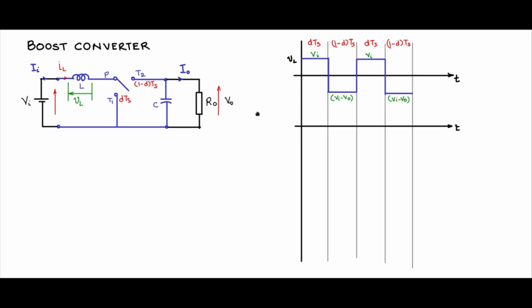So now let us see the current waveform through the inductance. I am drawing this average current here. This is average current flowing through the input, flowing through the same inductor. And the inductor has 2 parts, the average part and the ripple part. So let me call this In average and let me draw the ripple. I am drawing the ripple as a straight line and it has a slope. V is equal to L di by dt. So the di by dt slope, I have placed it as a straight line, linear fixed slope.